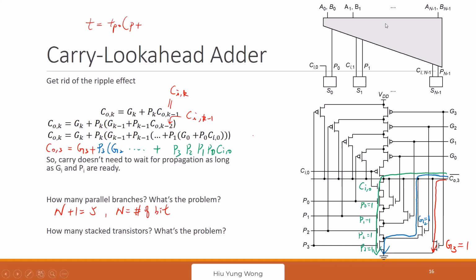I think I need to test you again in the final. FG divided by gamma, right? And P is related to what? The intrinsic delay, intrinsic capacitance, right? Every gate has an intrinsic capacitance, which is a function of the drain capacitance. So if I have 5 of them connected in parallel, then I have really huge drain capacitance. This delay is going to be large. Is this okay?